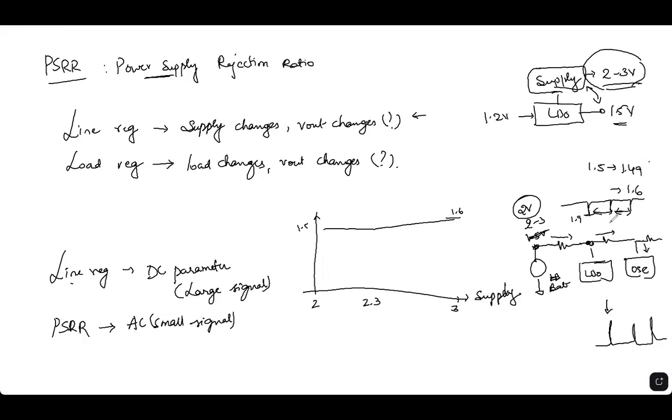It's a fixed interval, meaning anytime there is a periodic and repetitive pattern in current or voltage, you can always associate it to some frequency components. If the oscillator is working at, let's say, 1 gigahertz frequency, your current consumption may be typically every half cycle, meaning every 0.5 nanosecond there will be current being taken in something like this.